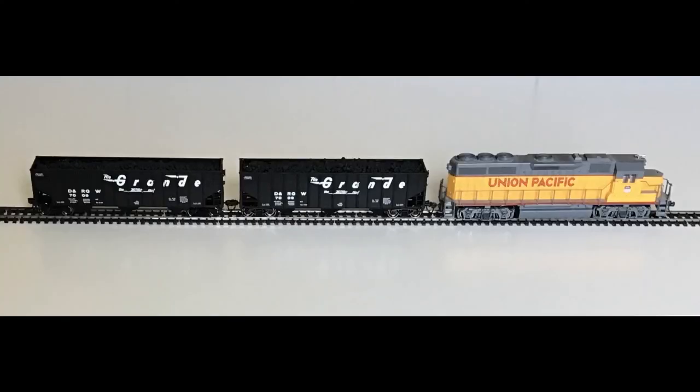In a real system, the loco weight and friction will probably not be negligible compared to the values of the truck. Again, no problem. The values can just be lumped with those of the truck. What we have described so far is voltage control, where an increase in demand voltage results in an increase in speed. It's an inherently stable system, because if the train comes to a rise and the speed drops, Vg will drop and Vs minus Vg automatically demand more torque. The speed will drop, but only to a limited degree. Other possible control strategies, and the one decided upon for the electric 9F, are described in the next part.